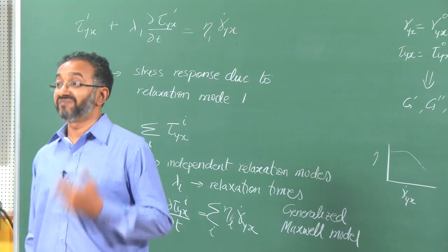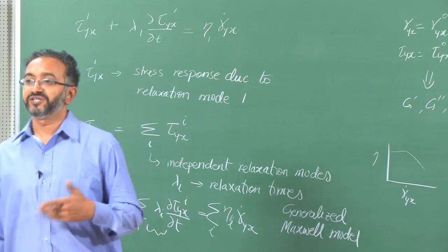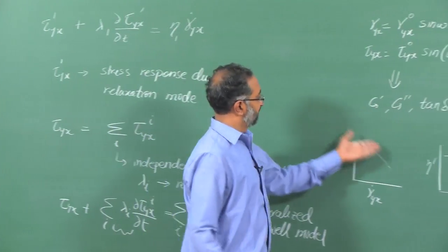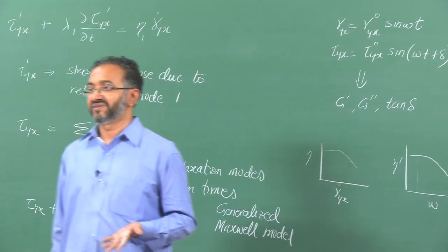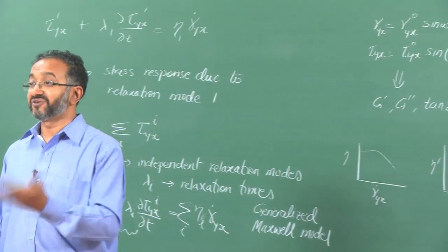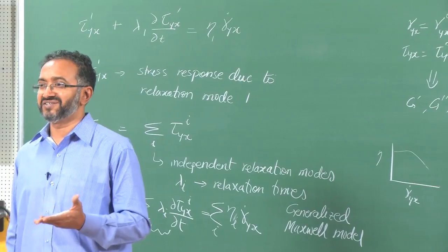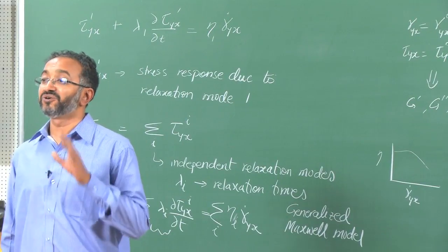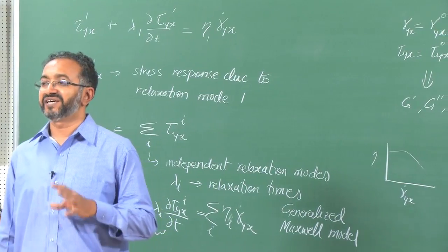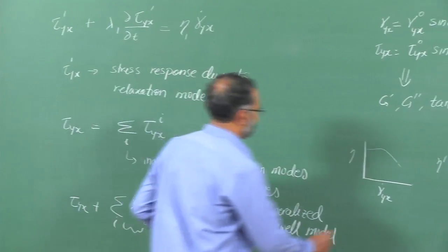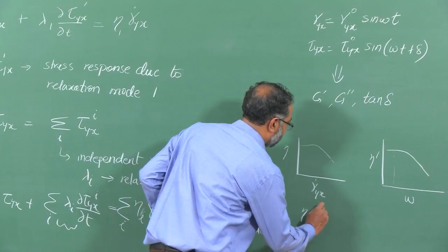So we realize that underlying mechanisms are necessarily viscoelastic, but if I choose to model this using a viscous model, I can do that, right. So if I use, let us say, a Carreau-Yasuda kind of model that we discussed, then I am ignoring the viscoelastic mechanisms, and I am saying I am only interested in looking at viscosity as a function of gamma dot yx.